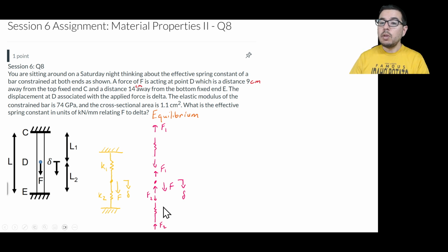Now, the spring below is experiencing the opposite effect, not tension, but compression. As we have a displacement going downward, there is a force going into this node in the middle, and so we need to have forces going into the springs here to represent the compression that this spring is undergoing.